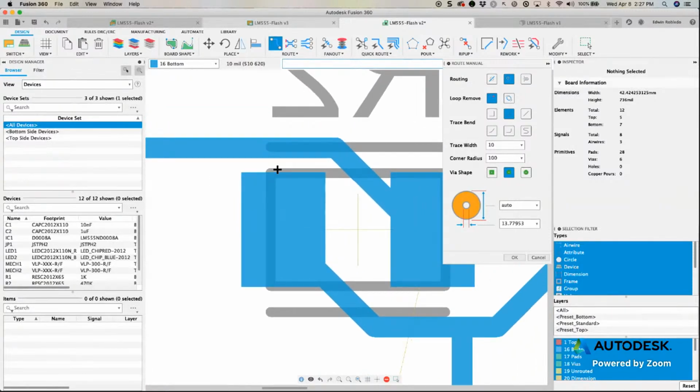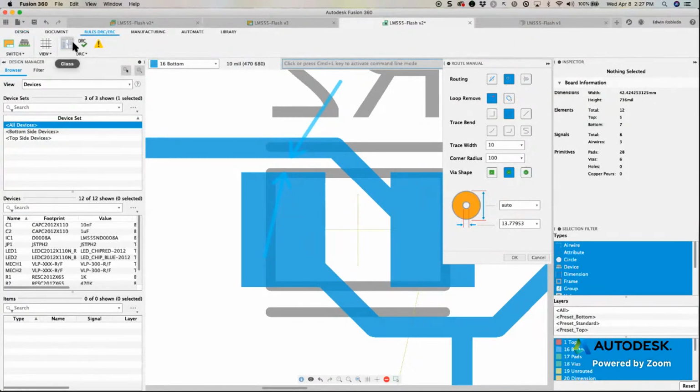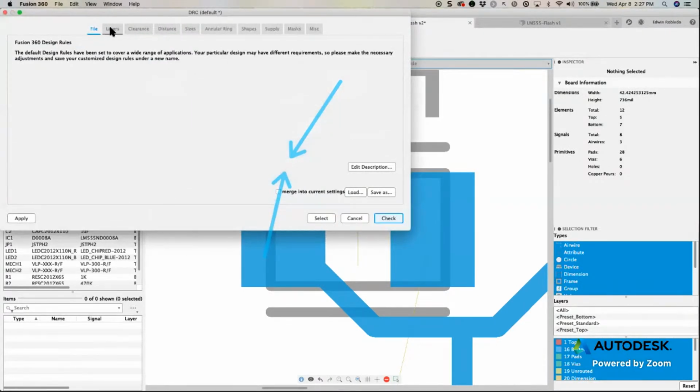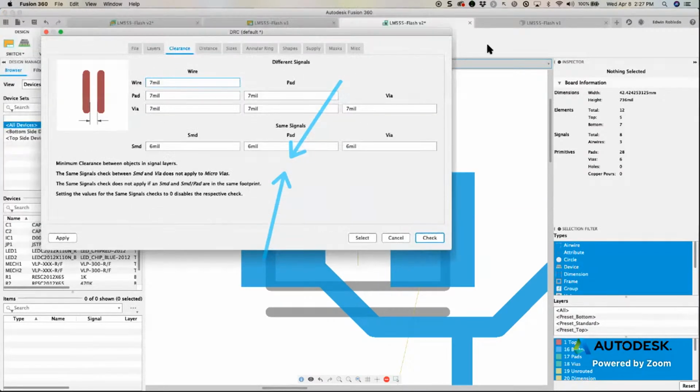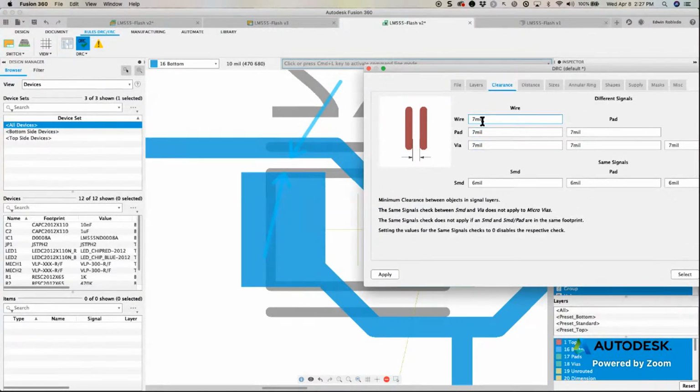That distance that we're seeing is the distance that is going to be allowed between this edge of your trace and this edge of the pad, okay? That's what we're seeing there. So that distance is going to be left there. We could go lower, but we could also go higher. You don't want to go too low. Okay. Now, also, let's talk a little bit about the next one, which is vias.